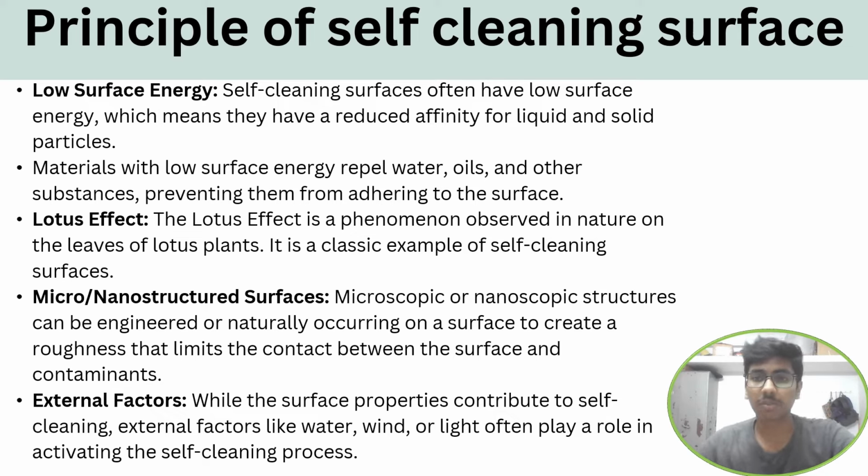The principle of self-cleaning surfaces. Low surface energy. Self-cleaning surfaces often have low surface energy, which means they have reduced affinity for liquid and solid particles. Materials with low surface energy repel water, oils, and other substances, preventing them from adhering to the surface. Lotus effect. This is a phenomenon observed in nature on the leaves of lotus plants. This is a classic example of self-cleaning surfaces.